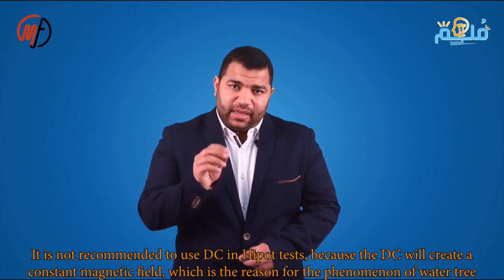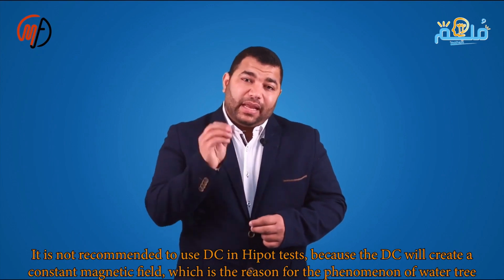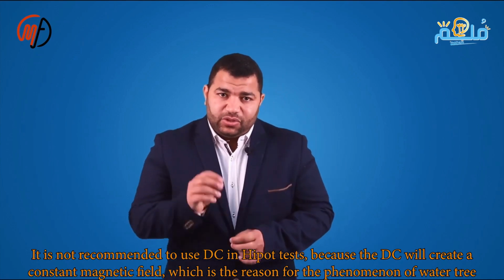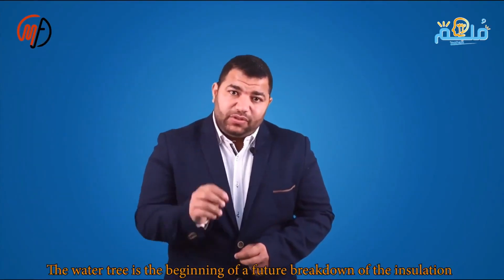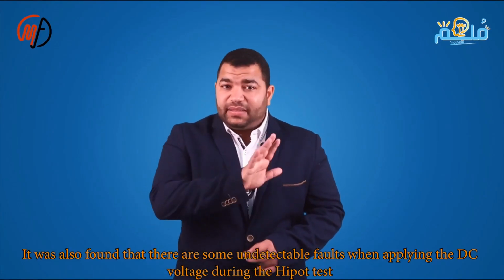DC supply in a hypot test is not recommended as it can cause treeing. Some defects are missed with DC. AC versus DC: AC is large, high energy. DC is small, less energy. AC doesn't affect lifespan and simulates actual voltages. DC can cause treeing. AC reveals most defects. DC detects thermal defects.